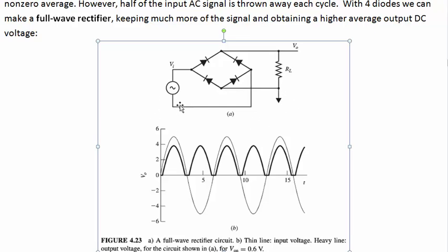So when you've got a positive voltage at the top of this voltage supply relative to the bottom, then current can go up out of it through this path and can come in from this path on the bottom. If the opposite's true, if we want to have current going out the bottom on the other side of the cycle, then it would go up this way and through this diode. And where does it come from? It goes through here. To get back to the voltage supply, it's got to go through this diode this time and back in the top.